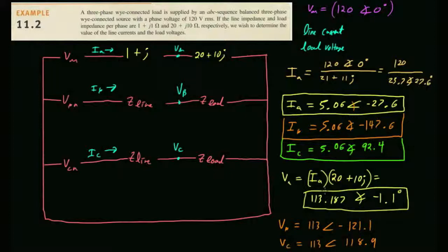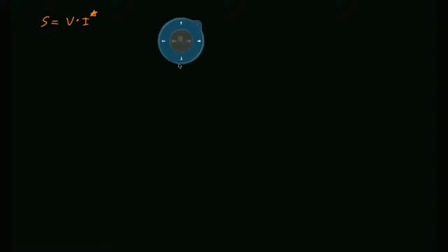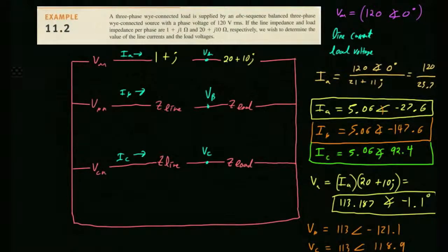Okay, but it'd be very easy to combine one of these problems with one of those problems, make a truly stinking exam problem. So let's think about that. In case you've forgotten, complex power is equal to voltage times the complex conjugate of current, and that winds up giving you a real part and an imaginary part. The real part is your regular old real power you've been calculating all along, and then that's imaginary power. That's the kind of power that you get in inductors and capacitors. Remember we talked about inductors and capacitors having average power of 0? They have average real power 0, but you can actually calculate imaginary power, and that's where your inductors and capacitors come into play. Anyway, I'm just saying, consider the possibility that those could be combined.